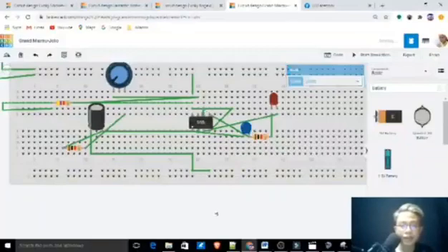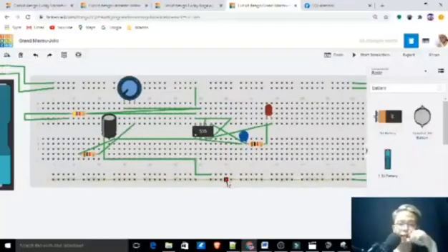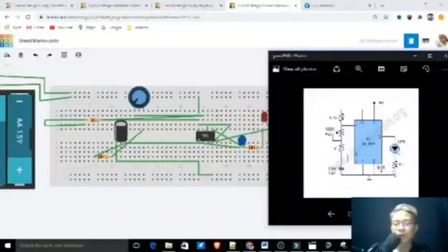Okay, so you will notice that we're connecting that one to pin 6, because it was hiding, so you can see it. So I just put that one in the upper side. So that one, 1 kilo ohms to the 100 kilo ohms potentiometer. So here, connect there, from the terminal 2 of the potentiometer. This one side in the middle is the wiper, and this one is our terminal 1.